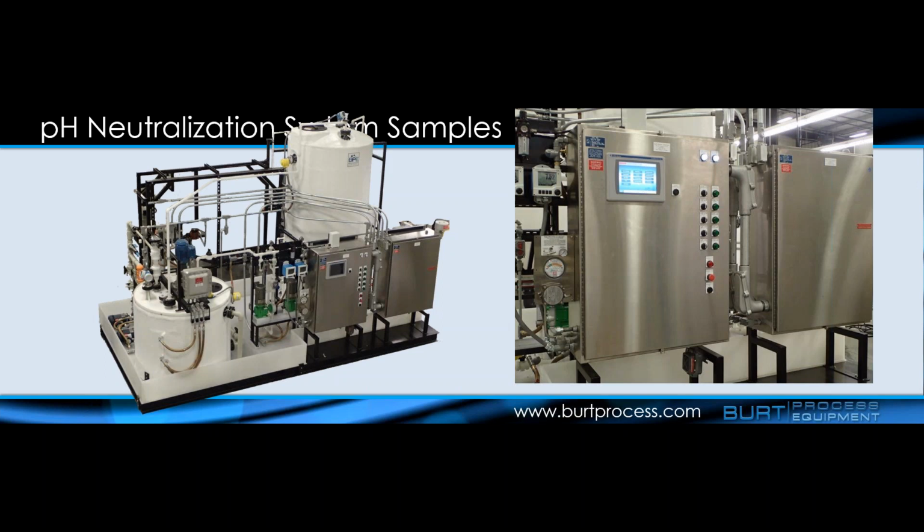I've seen it happen before, particularly more in accidents where, say, somebody mixes an acid and a base together, that will just boil basically right in your face. So yes, that is something that does come up. Generally, if you do good system design up front, it shouldn't happen unknowingly unless somebody puts something incorrectly down the drain. But yes, pH reactions can actually be very exothermic.